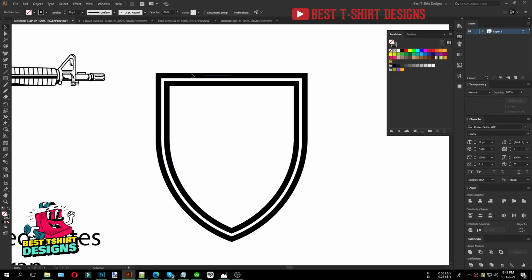And now for the offset path one, I don't want it to cover all the area. I just want some simple shapes just in the corner area. And how to do that? If I take this add anchor point tool again, and if I click here, kind of this position, then again a position here, then I click here, and then another one here, just to make some random areas. And then you can see I'm clicking here and then another click here.